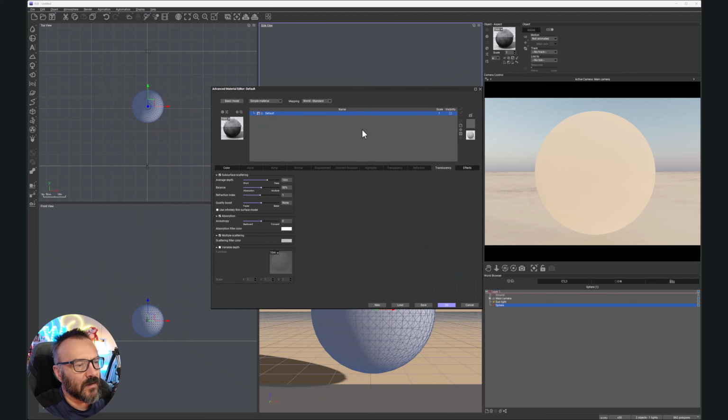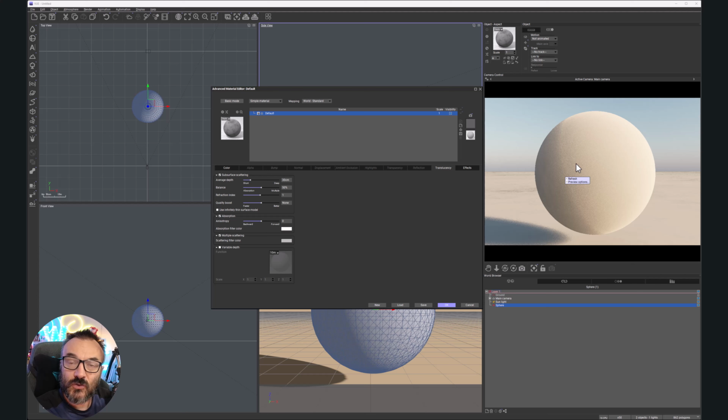And of course, we have here a value of 10 meters deep. We can reduce this depth, we'll make it a little bit shorter. And as we're making it shorter, you can see light absorbs faster. So it's a more dense material in some cases. And we can even do a little bit less, 30 centimeters. And you can see the sun coming from the side, and the light absorbs more. Notice we already can see the grain here as well. And this grain is happening because the light absorbs too much. And after so many bounces, it just stops. So we have this grain.